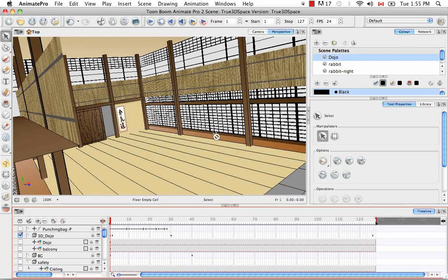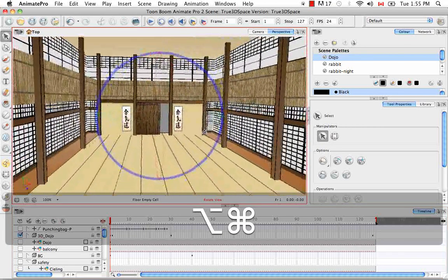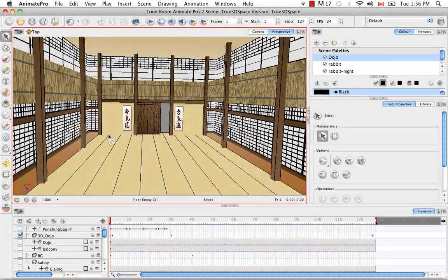So for example, this floor with this light brown portion here, all these black lines, any of these textured lines, I didn't finish doing the texture here, any of the dividing lines for the tatami mats, all of those are on one layer because I wanted to flip this layer and all of its details together. Anything that you need to flip by itself or rotate by itself has to be on its own layer, which is the only other thing you really need to know.